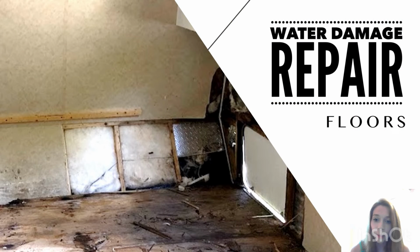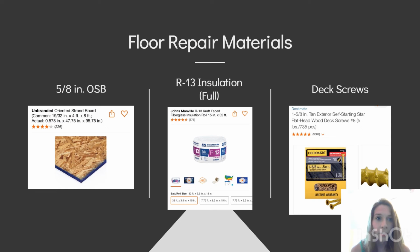Okay, now that we have some basics of repairing water damage, we'll go into each specific category. So we're going to start with floors because it's the easiest, and we'll work our way all the way up to the roof. Now these are some basic materials you need to repair water damage on your floor. Keep in mind that the 5/8 inch OSB may not be what size your subfloor is, so make sure to measure how thick your specific camper subfloor is and buy the materials to match.